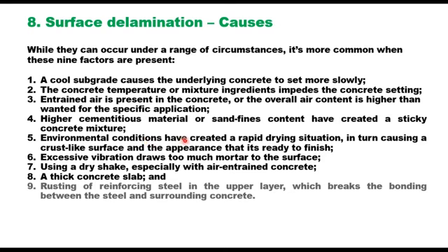Environmental conditions can also result in surface delamination. Excessive vibration draws too much mortar to the surface. Using a dry shake, especially with air entrained concrete, a thick concrete slab, or rusting of reinforcing steel in the upper layer, which breaks the bonding between the steel and surrounding concrete.